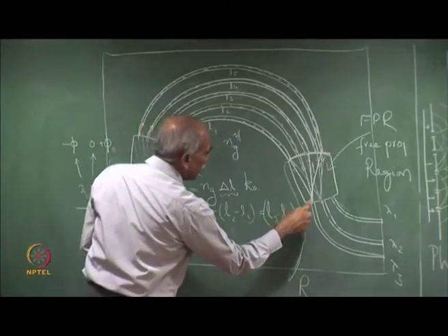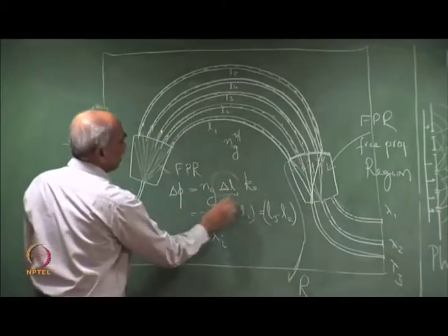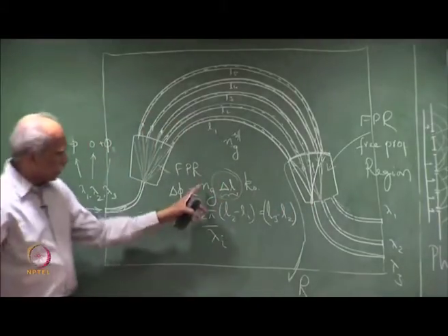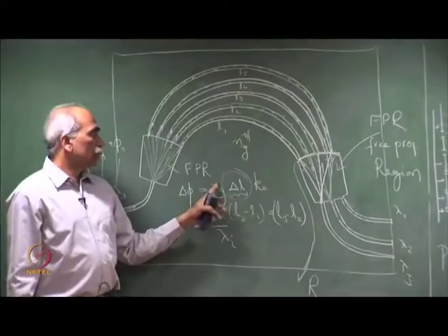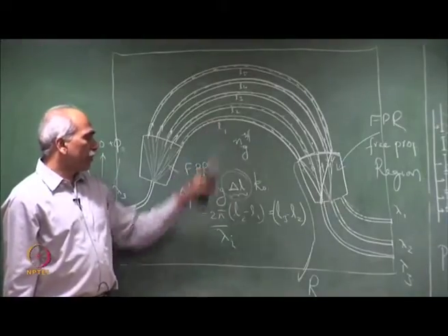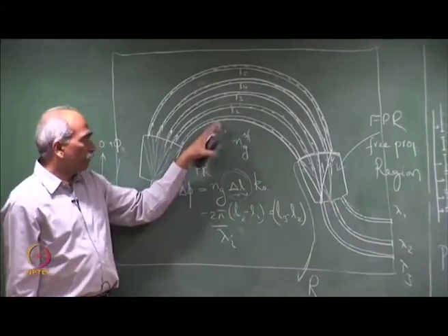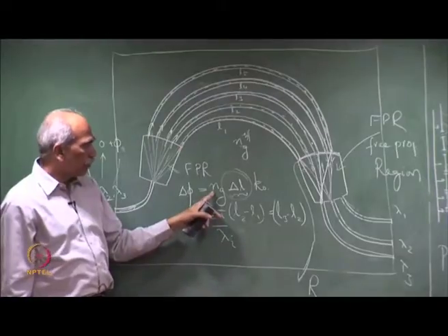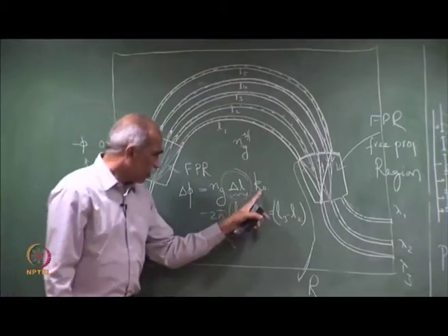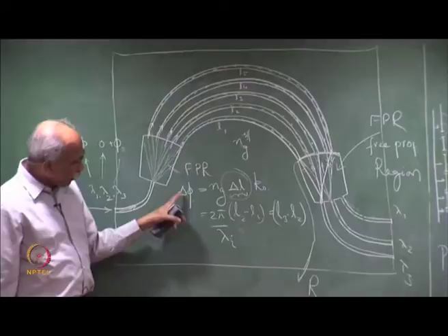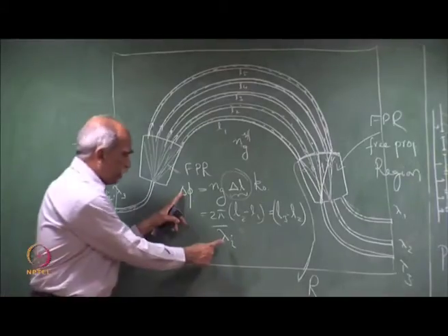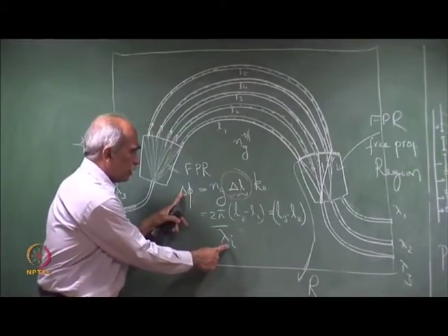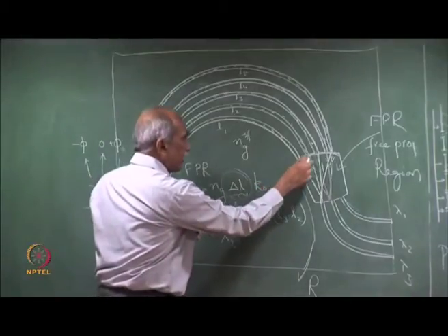So, that is determined by delta L, because Ng is determined by the dimensions of the waveguide, the refractive index and the width of the waveguide, the mode effective index, and k naught contains the wavelength. Therefore, delta phi is different for different wavelengths. It is constant from one waveguide in the array to another.